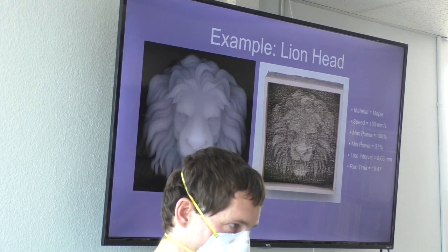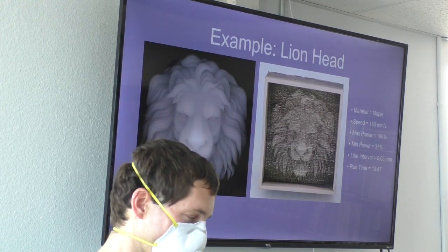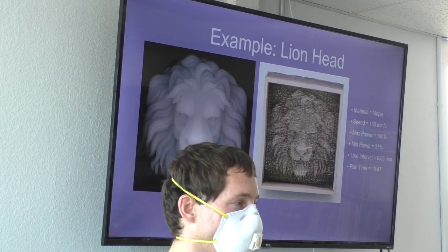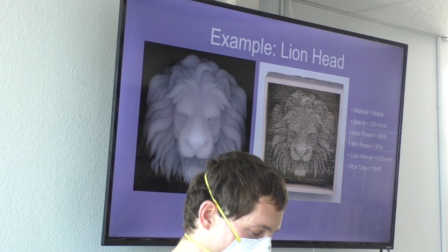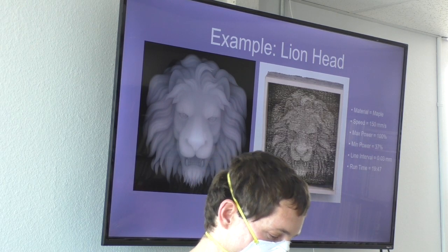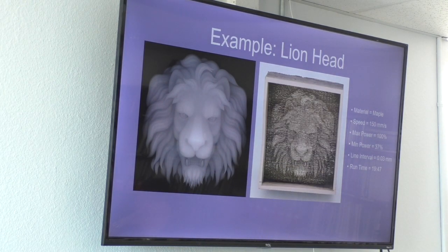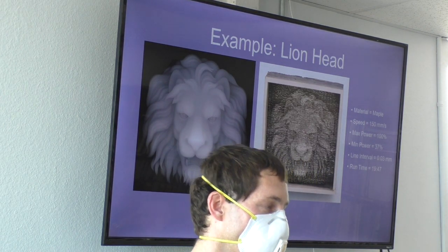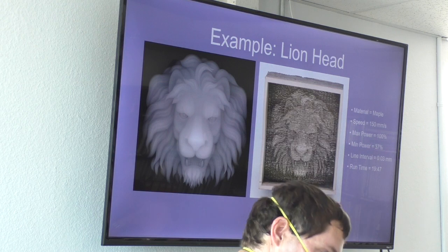So going on with the depth of cut thing, this was not 3D engraving, but since we're on the side, we'll get to it. So I wanted to see how deep it'll actually go. I got something quite thick and made a little triangle out of it so that I could put it on the laser such that the top was parallel to the bed, and then I would cut across it down its length.